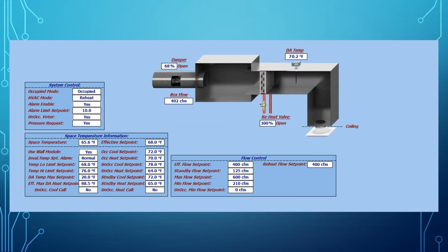But at this point in time, coming back into our scenario, we've got a couple of ideas where we could be. We could have too cold a hot water, or we could have a malfunctioning reheat valve. Those are our current prevailing theories. And I think they're both very valid theories, definitely could be those things. But given that we don't have access to the space right now, we can't really go and investigate this hot water valve to see if it is working or not. So we can check on some other data in the process.